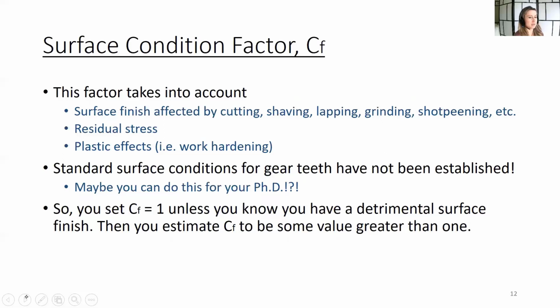So best practice is to just set CF equal to 1, unless you know that you have some detrimental surface finish, then you have to estimate your CF to be some value greater than 1. For the purpose of this class, we are going to go with CF equals 1, because again, these values haven't even been well established.